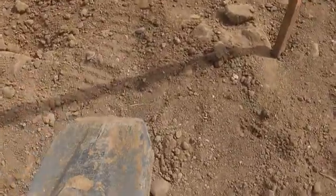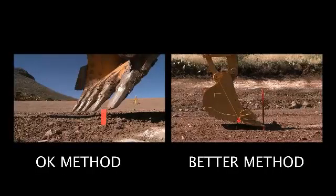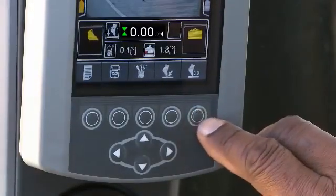Place the focused part of the cutting edge near the reference elevation. Setting the reference with the bucket level will eliminate most errors from teeth wear. The benchmark icon displays benched.